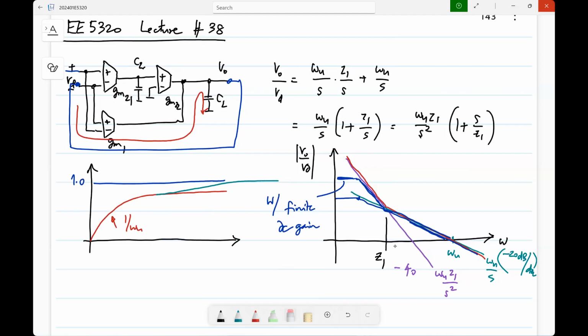So the bottom line is that in design, in the two-stage Miller op-amp, let's say you had a poor phase margin, what would you adjust? In the Miller op-amp, you have poor phase margin, what component would you start playing around with? CC, right? I mean, you can play around with many other things. Again, when I say we want to change the stability margin, the idea is you shouldn't change anything else.